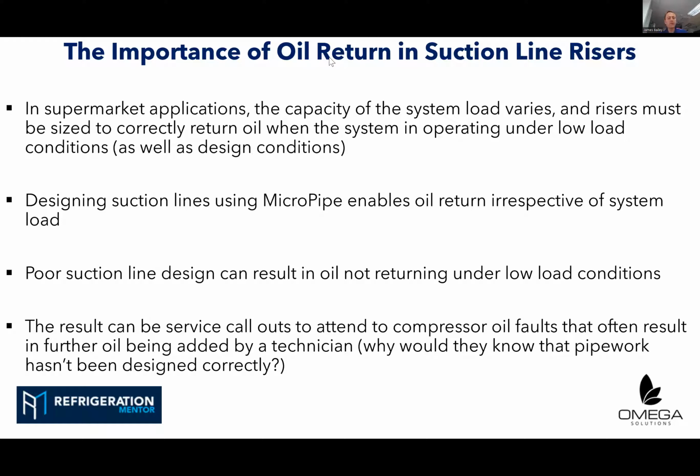If you incorrectly size, you could end up with oversized pipework. MicroPipe compensates for that. The real problem in designing suction line pipework, especially if you're not using MicroPipe and you're working from charts and from first principles, is grabbing a hold of that dynamic factor.